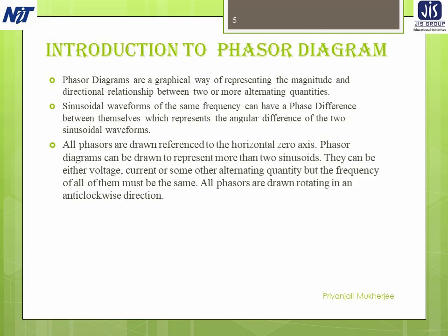Now voltage is simply energy or work per coulomb and cannot be classified as a vector. Current is also not a vector quantity because it is the flow of electrons through a wire, but keep in mind that any sinusoidal quantity at a given frequency is completely specified by its amplitude and phase angle, hence its similarity to a vector. Now to make the difference, the term phasor has been used instead of the term vector for representing graphically the magnitude and phase of a sinusoidal voltage or current.